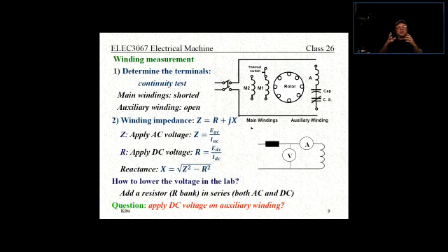In the single phase, we're not going to create the revolving magnetic field right away because we won't be able to make it spin around the stator, as we only have one phase. So it's just like a pulsating field, but one that stands still. That's why we need to introduce the out of phase auxiliary windings just to start it. Once you start it, we just disengage that, and the motion is going to sustain it. The rotor hits the pulsating magnetic field at certain times, and that sustains the motion.